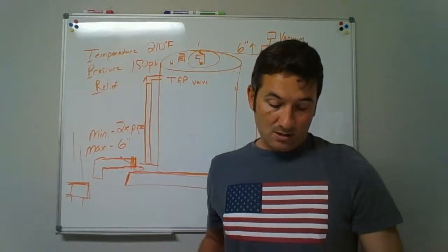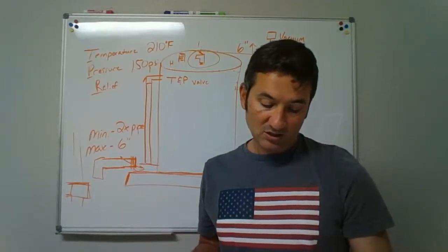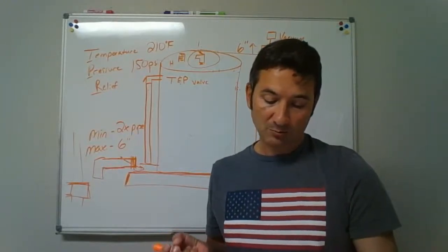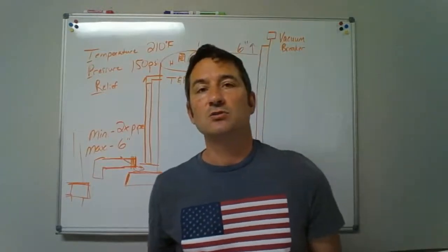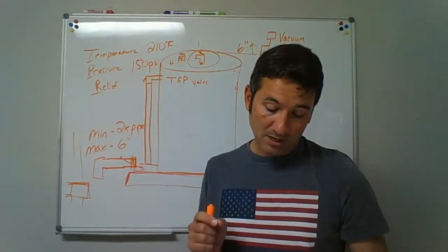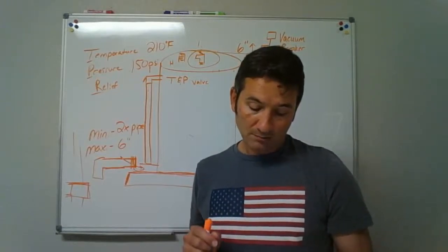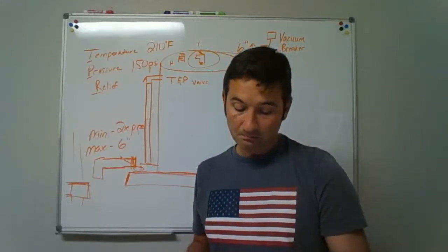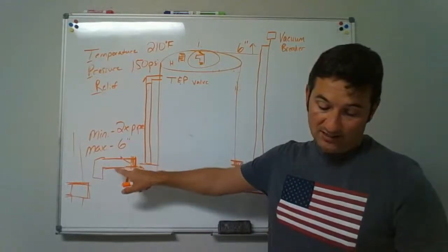Okay. You can have a galvanized steel or aluminum pan having a material thickness of not less than, and it gives you the thickness, number 24 gauge for steel, and number 26 gauge for aluminum, or other pans approved for such use, depending on the type that you could use. Some plastic: electric water heaters may rest in a high impact plastic pan of at least 1/16 inch thickness. Water heaters mounted on a concrete floor with a floor drain are some exceptions, okay?